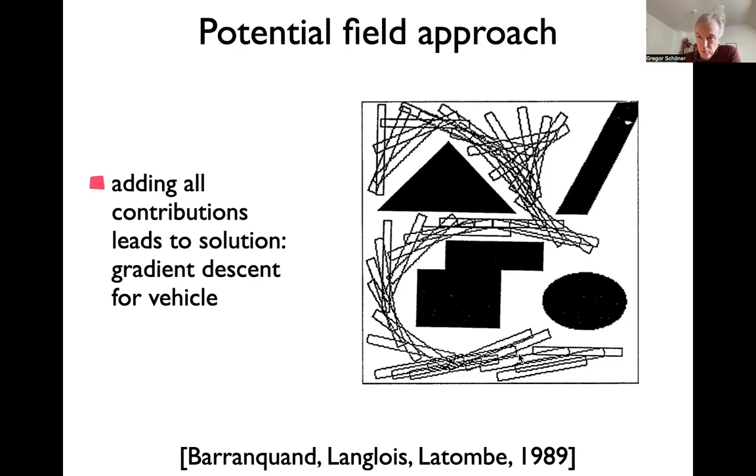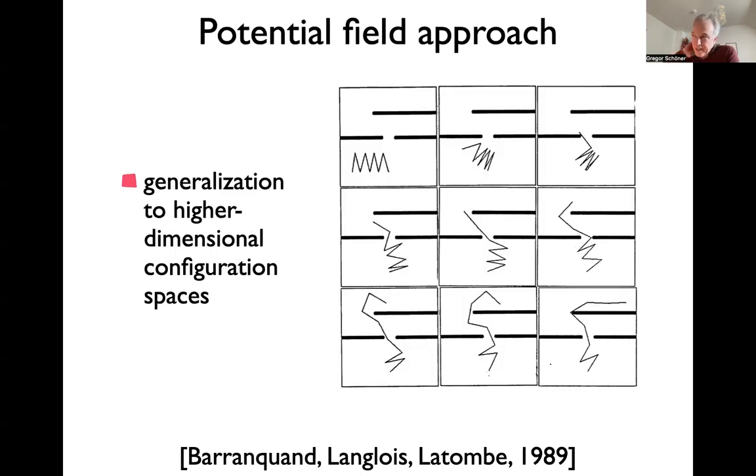So something we didn't do so far, right? We did a very trivial form of obstacle avoidance where the robot is a circle, so with just a safety margin. So that's a much easier thing. So it doesn't matter in which orientation you go through an opening. Here it matters. In fact, the potential field approach is very flexible that way. That's why it can be extended to arms.